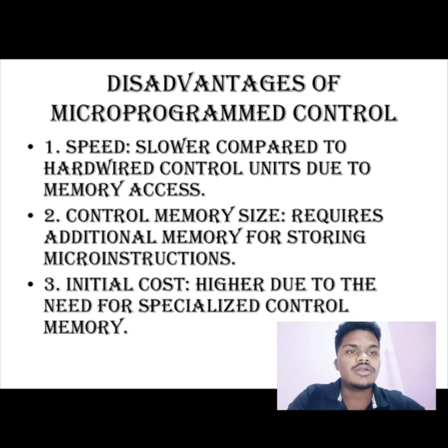Disadvantages of the microprogram control. First one is speed. The microprogram control is slower compared to the hardware control due to memory access. Second one is control memory size, requires additional memory for storing micro instruction. Third one is initial cost, higher due to the need of additional memory or specialized control memory compared to the hardware control units. Next, in the next slide, I am going to discuss about the applications of the microprogram control.